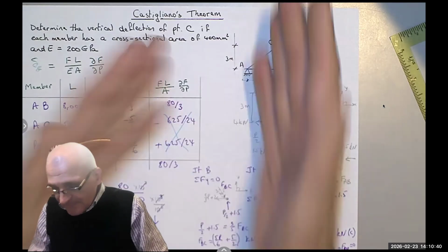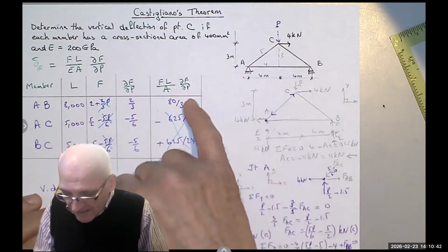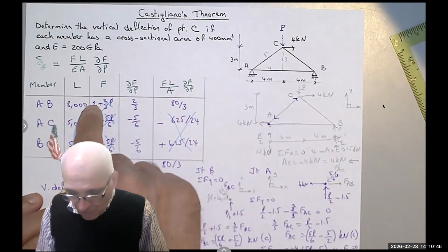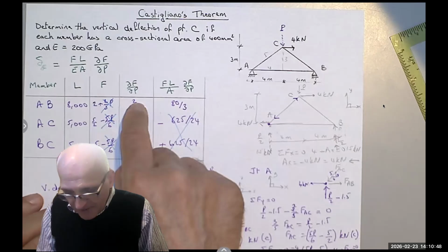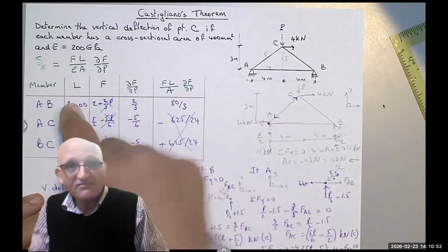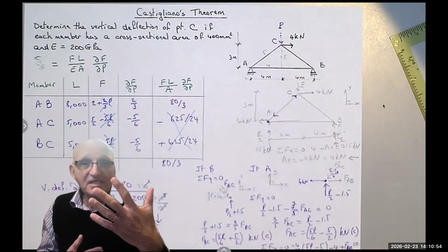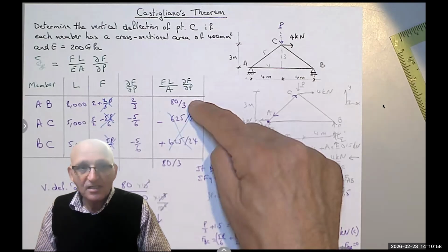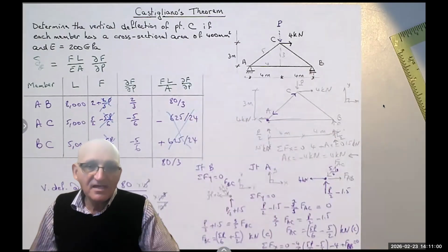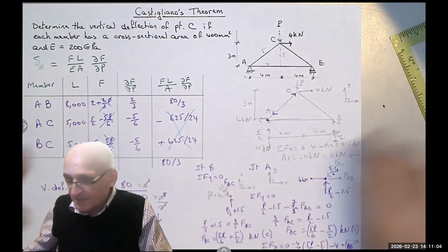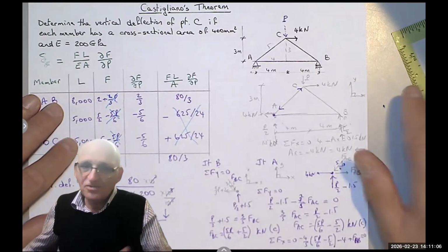At the end of the day, this would be in terms of P, because you are multiplying. This is P over 2 times 1/2, which would be P over 4, times 8,000 would be 2,000 P. Divide by 400 would be 5P, but P is 4, so you write 20 kilonewton, just 20, and so on and so forth. There is nothing more you can do, and you will get the horizontal displacement very easily. I think you can do it on your own.